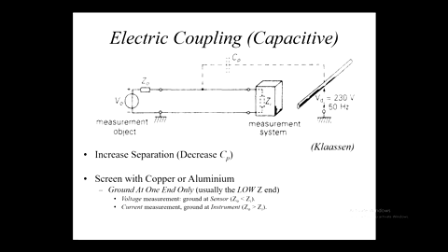Probably some students in the workshops, I've got them to hold on to an oscilloscope lead just to see that the mains signal comes in, and that can be 20 volts or so, which is sort of between this capacitive impedance down to ground through whatever value goes through the capacitor or through your boots down to ground.